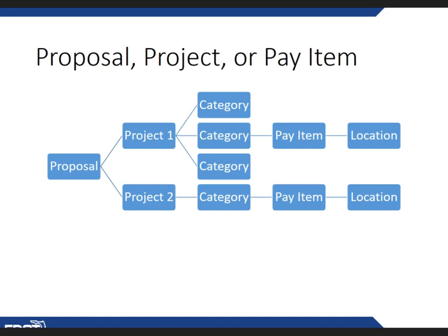You may also have a number of pull boxes for your signals. Amazingly enough, they're usually located near signals or other signalized intersections, or even some of the mid-block crossings. But if they contain the wiring for signals items, they need to be in the signals plans.